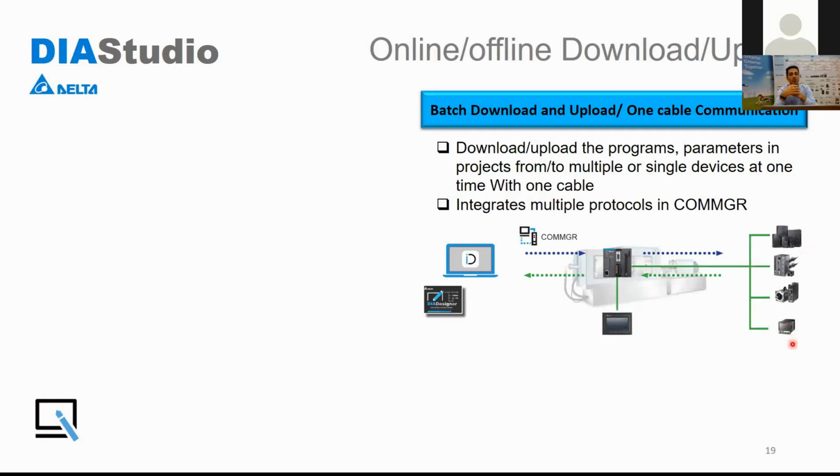Normally, you need to connect to the first PLC to download, then the second one, then go to the VFD to download, and go to the ASDA-Soft for the servo. But here in this designer, since they are all included in the project and all connected at the same time, you can download all in one.